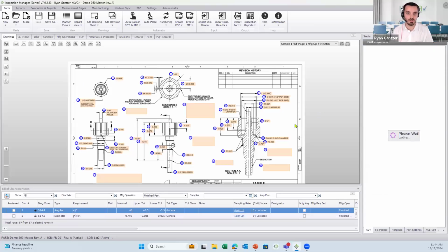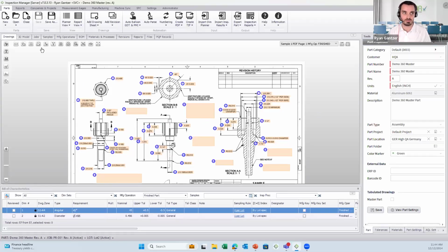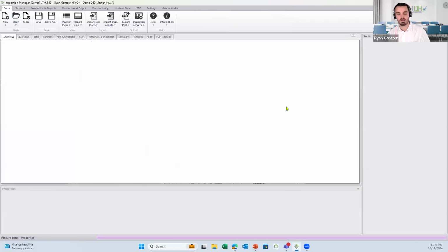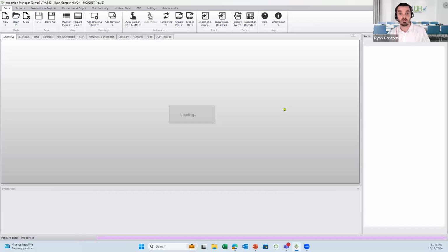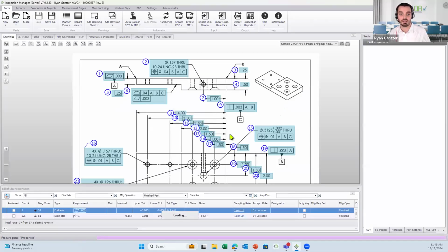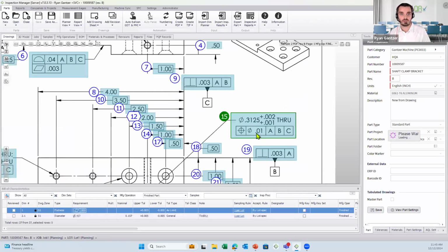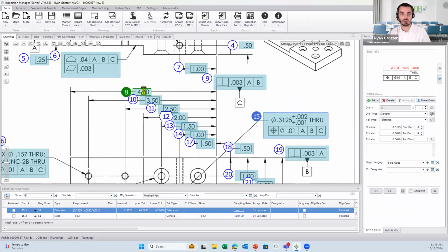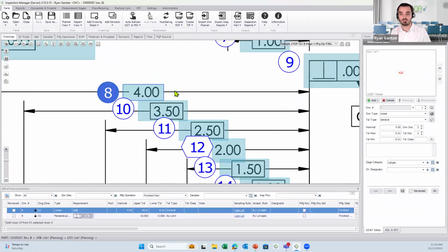Okay. Yeah. So if the print has the tolerancing on the dimension itself, let me pull up that print that we were looking at most of the time today. If the print has the tolerancing on it itself, like this plus plus, we will bring that in. If it's not on the dimension, this plus or minus 10 thou, that's coming ultimately from these part categories that I keep referencing, which again is a series of defaults and preferences.